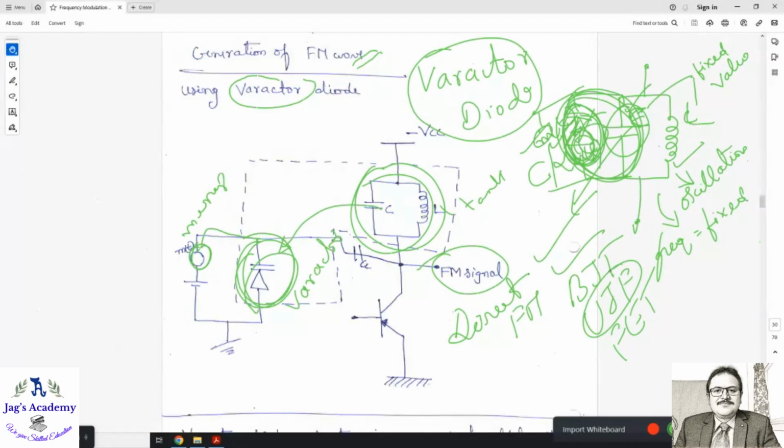There is a relation you get: transconductance. Do you know about this? Transconductance will vary according to the input voltage. You have an active device whose capacitance between its gate and one more terminal will vary according to the input voltage. And if you make that circuit parallel to the tank circuit, the applied voltage will vary the capacitance, and capacitance will vary the frequency of oscillation. Have you understood? Ultimately, the tank circuit is very important, that's all.